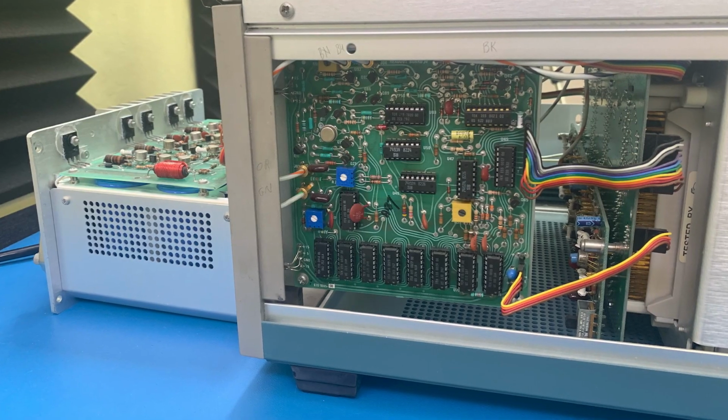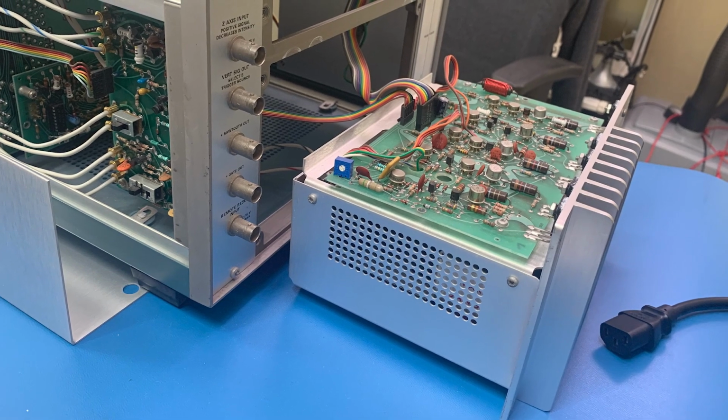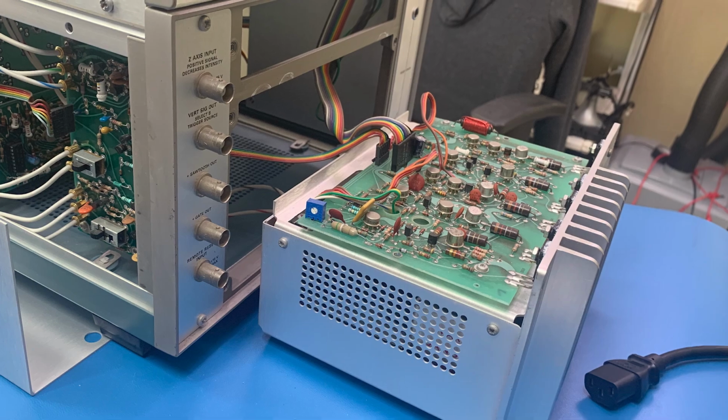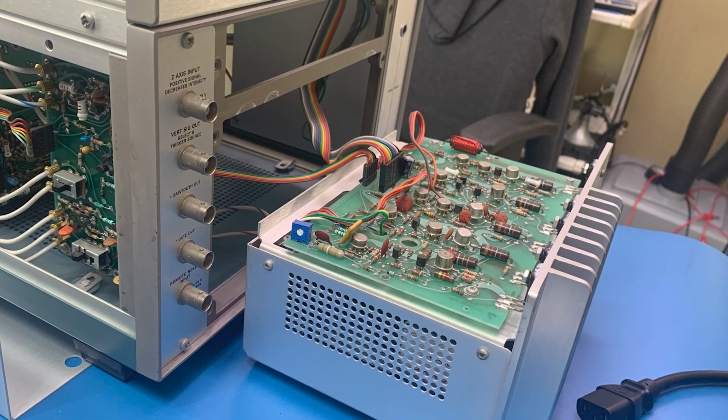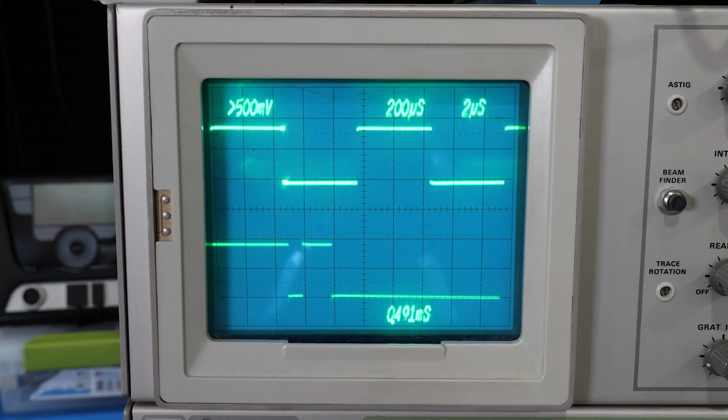On the back, the power supply module not only comes out, but shipped with a cable long enough to remove it from the frame while in operation. Back in 1978, switch mode power supplies were relatively new. And back then, just in general, instruments were made to be much more repairable. Crazy idea, right? I skipped over this in the video, but this scope not only shows the time-based times on screen, but also the delay times. Believe it or not, this was a super uncommon feature for analog scopes.